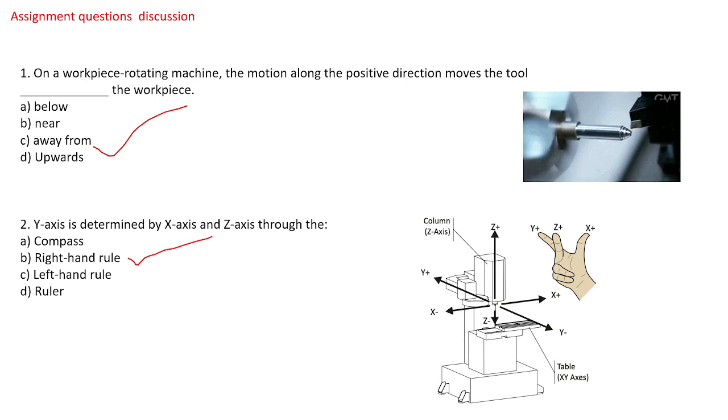But laser has some limitations because it creates subsurface damage in materials, and post processing is quite difficult to avoid the flame ignition which happens in the workpieces. We are facing that right now.